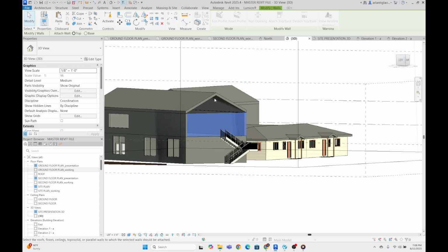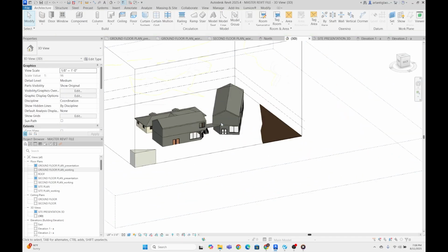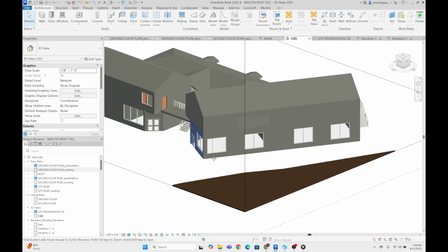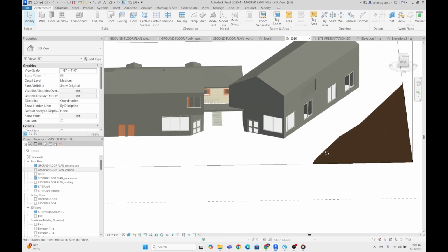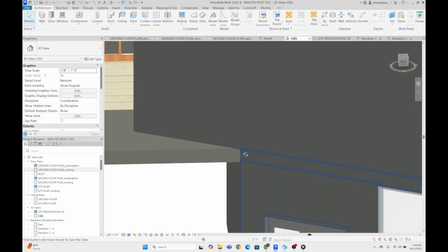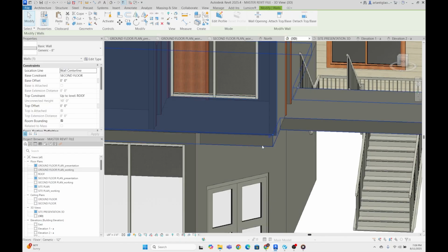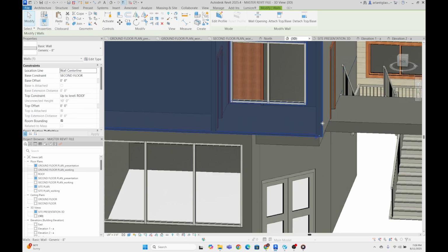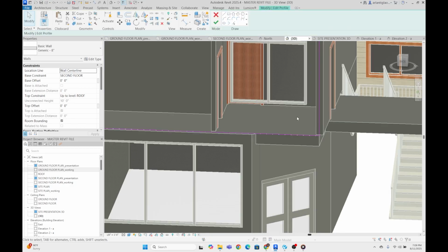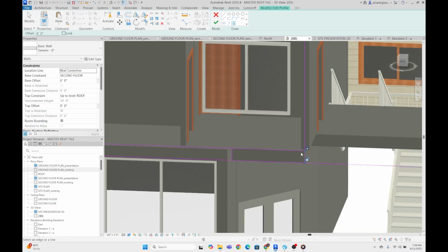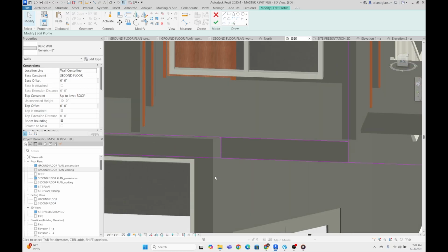I'm going to connect this. So you may notice around here that the wall is not necessarily overlapping between our drawn floor here. You can supplement that issue by using that tool we just learned and using the pick line tool to go along the base of our floor here.